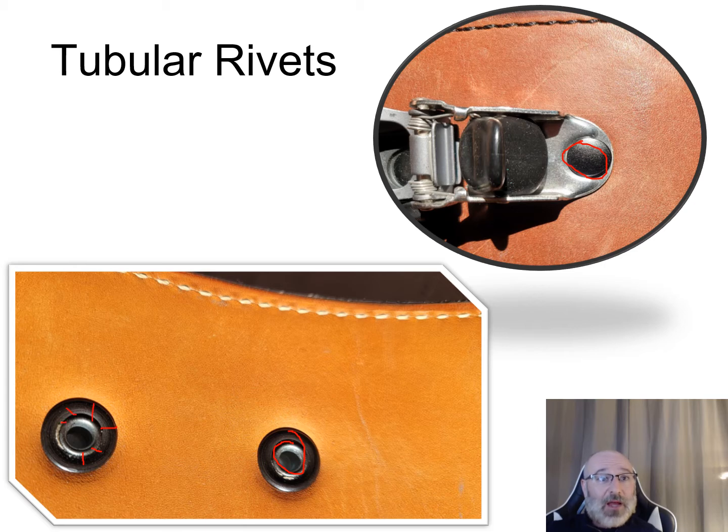Now I've done manual testing with these on tension testing machines to make sure that this is not going to pull through. Now I'm not pulling this in pure tension, so the force is going to be coming across, going in this direction here with my buckle as it pulls with the leather strap. So that right there is going to be causing the force to go and shear this right here rather than putting it in pure tension.